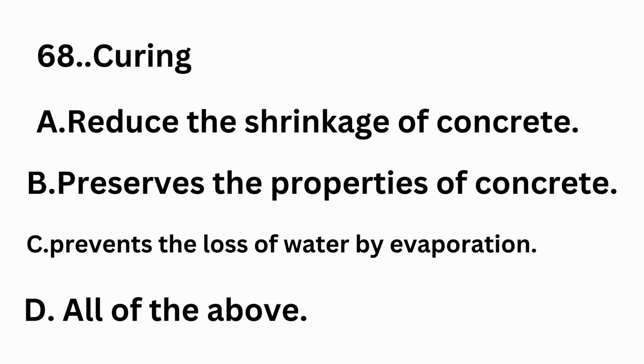68. Curing: A. Reduces the shrinkage of concrete, B. Preserves the properties of concrete, C. Prevents the loss of water by evaporation, and D. All of the above. Curing is the process of preventing the loss of moisture from the concrete. So, all the options are correct.